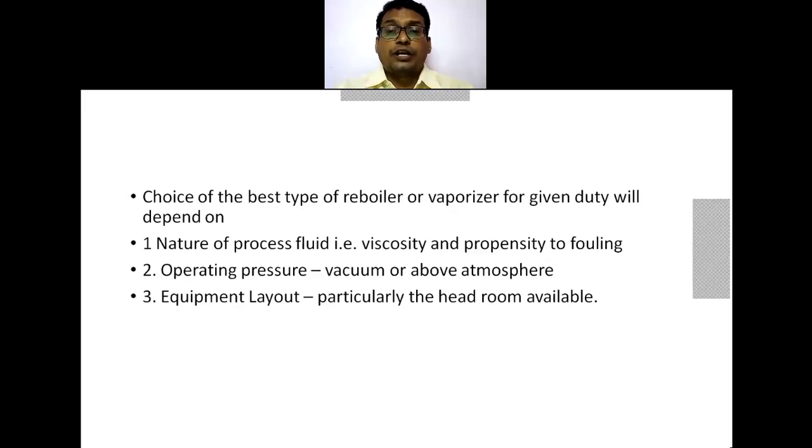Then the operating pressure, whether the distillation column is at a higher pressure or under vacuum, and accordingly the selection of the reboiler is based on the operating pressure.